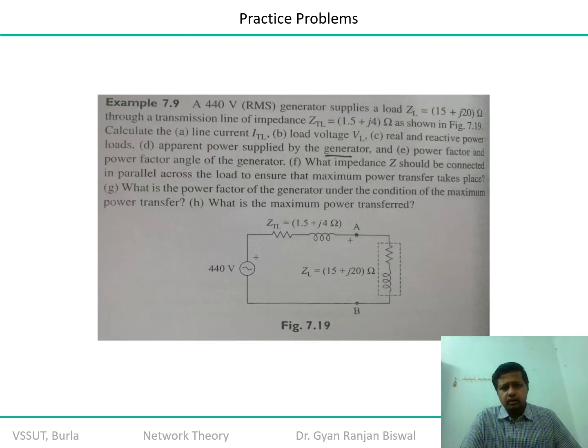Okay, very interesting one. This is the simplified model of source, power generation, power transmission and distribution, and at the end of the day the load, with the Thevenin impedance, the circuit impedance, the load impedance, and the Thevenin voltage. So it's a simplified model irrespective of any degree of complex networks.